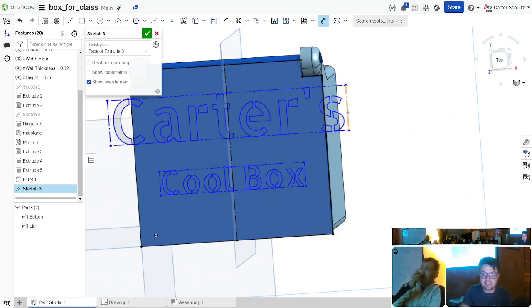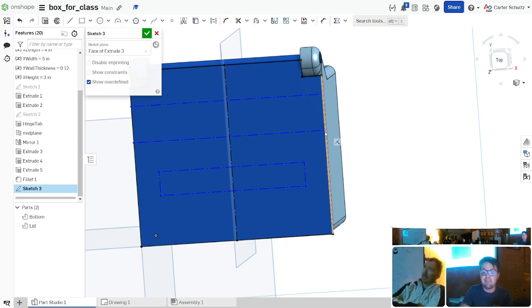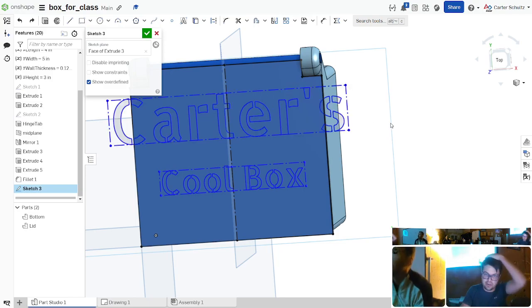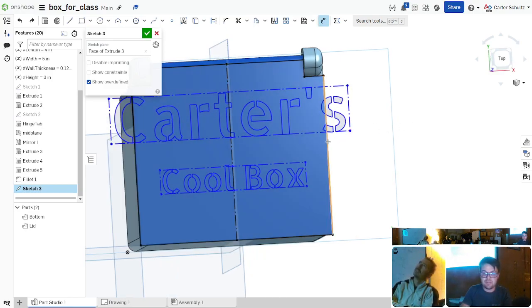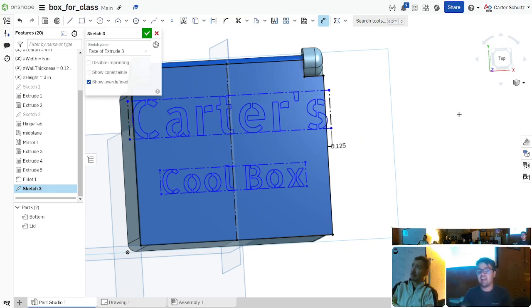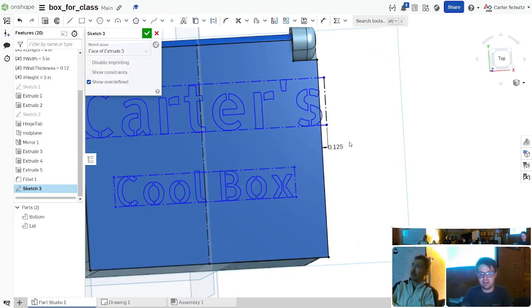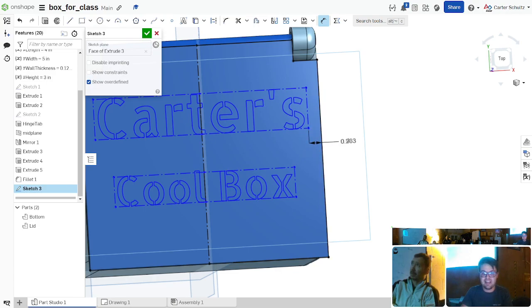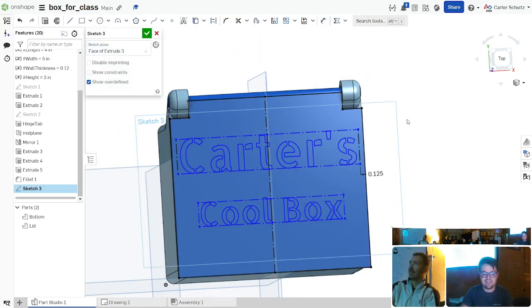We want to make the lines a good size. So what I'm actually going to do is grab this edge. I'm manually dragging that to this side before I add a dimension. And let me undo that and show you guys why. If I try to dimension this point to this edge right now, dimensions always have positive value, and that means it gets dimensioned on that side of it. And you can't put minus 0.25 in there. OnShape doesn't let you do that, and almost no CAD software does. I want to get it on this side first, and then I want to say hashtag wall thickness, because reuse variables. Very, very nice.